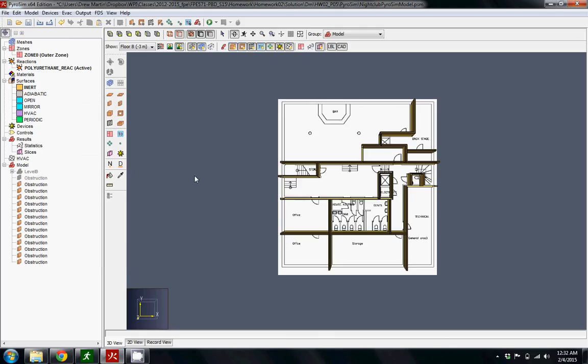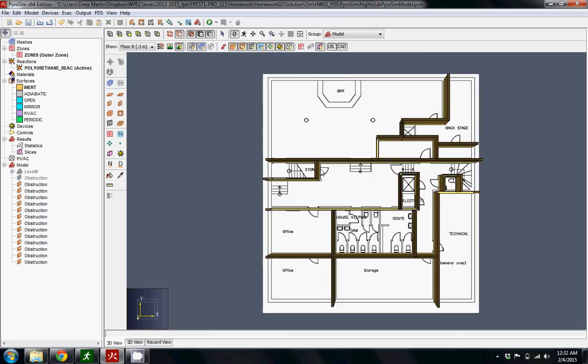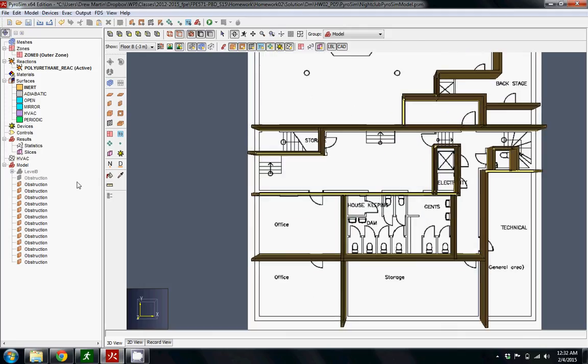Okay, so for this exercise, we're going to show how to make the wall openings that we need to represent doors and the staircases that we're gonna have in the model. To do that, we use this tool over here. This is the wall hole tool. There's one for slab holes. So if you want to draw a hole on a vertical plane, you can draw a slab hole.